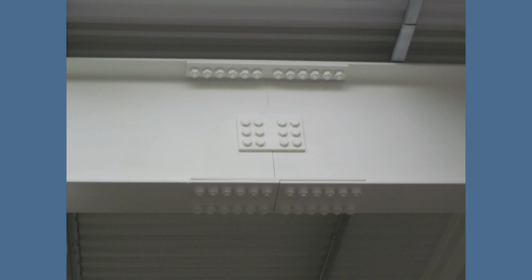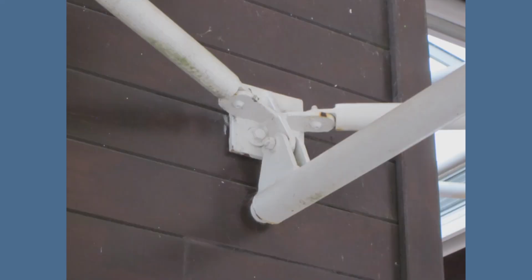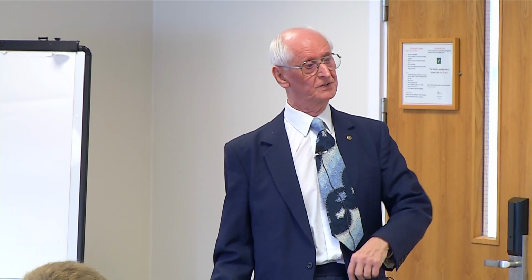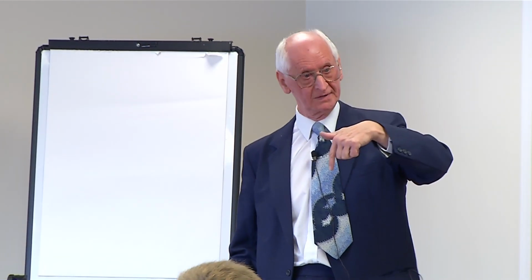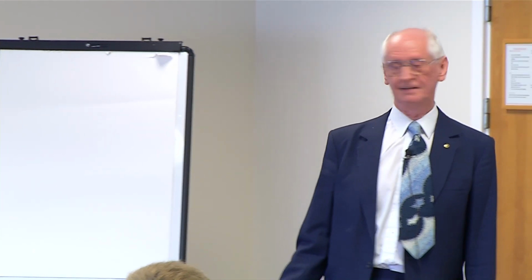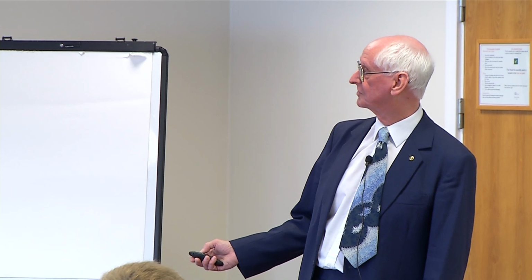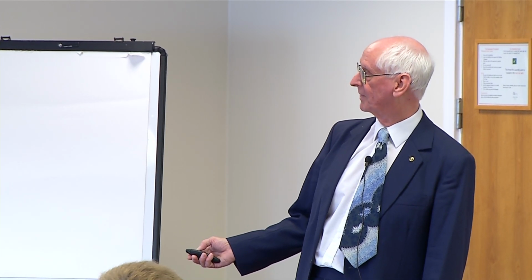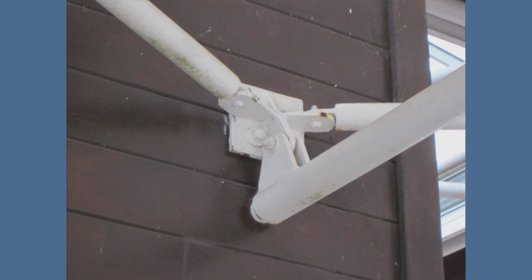Yes, not good. And how you put the bolts in is important. This is a canopy. And you note the bolt here has been put in upside down. Now, in the event that the nut comes loose for any reason, the bolt will fall out and the canopy will collapse. If you put the bolt in from the top and the nut comes off, the canopy will still stand. So it is really important when you look at structures to see whether they were paying attention or not, because if they didn't pay attention to this, they may not be paying attention to other things as well.